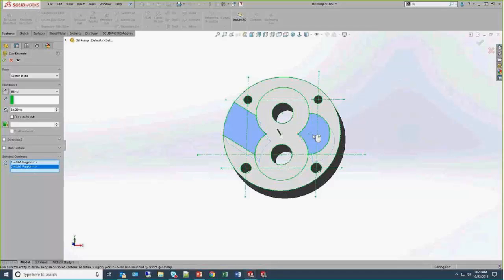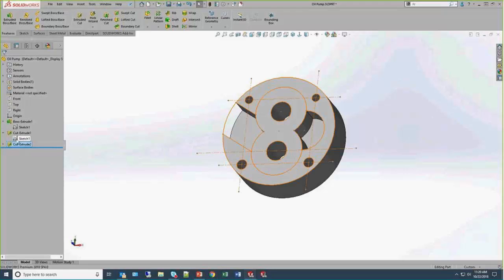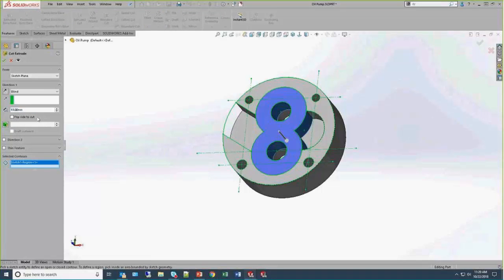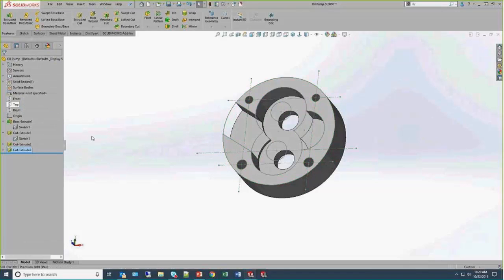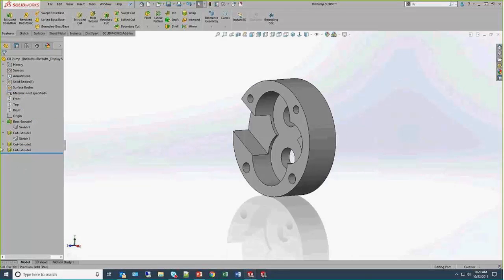That's the one thing you do have to understand, is I really can't do anything crazy with adjusting sketch planes or anything like that. But as long as I can reuse this sketch, I can essentially build this feature from one sketch and leverage it again and again and again. So it's a nice way to create one more complex, powerful sketch, and then all the features share that same sketch. We've got one sketch that contains all that design intent. Really makes it easy for any type of design changes that you may need to leverage.